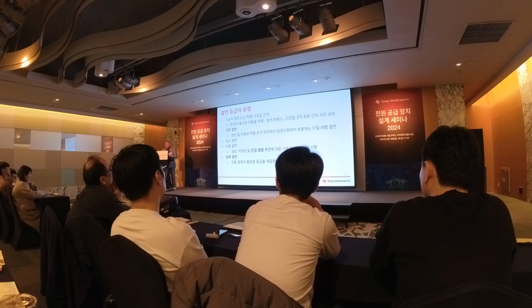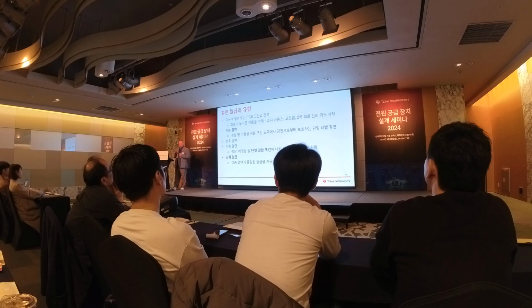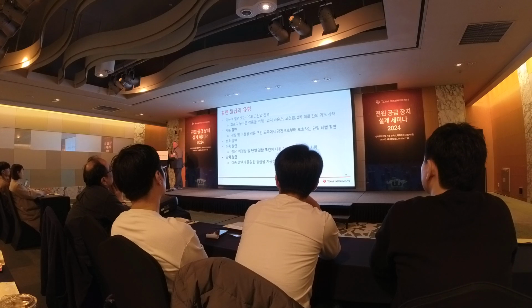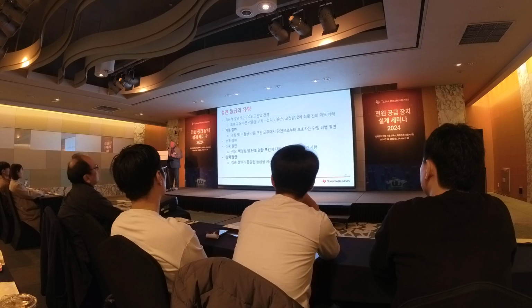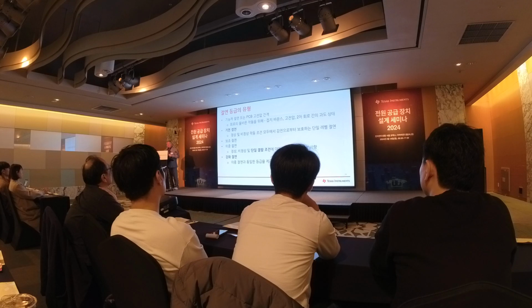If I look at basic insulation, it is a single level of insulation to protect the user from electrical shock, in both normal and abnormal operating conditions. So for basic insulation, it's a single level of protection. If I look at supplementary insulation, this is independent insulation applied in addition to basic insulation.